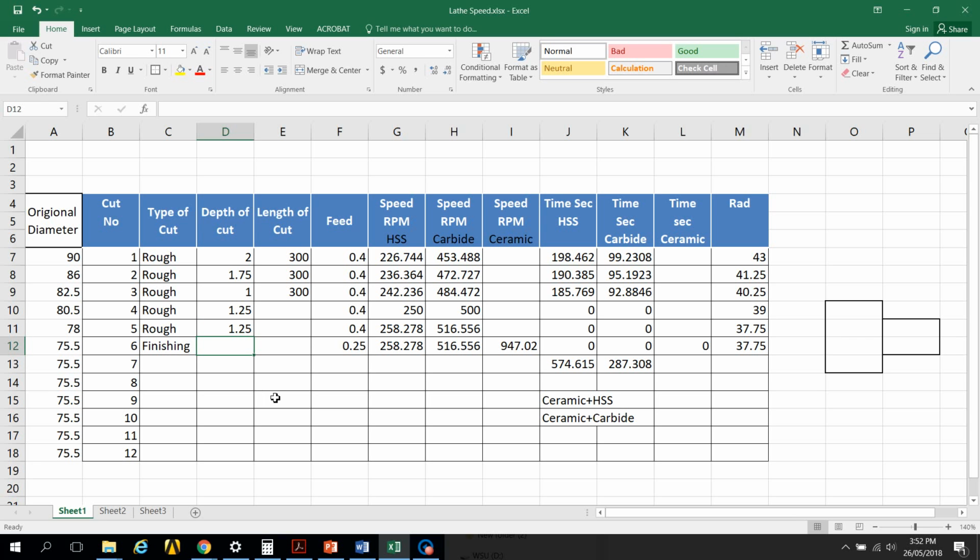Now each time you decrease the depth of cut, you make your cutting tool live longer, as well as reduce the orthogonal forces during the cut operation. This will cause fewer changes in the characteristics of the material you are cutting, and also increase the lifetime of your cutting tool.